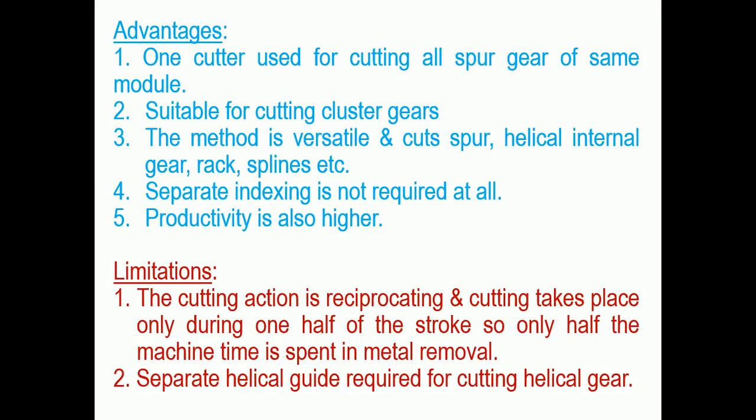What are the limitations? The cutting action is reciprocating and cutting takes place only during one half of the strokes, so only half of the machine's time is spent in metal removal, and a separate helical guide is required for cutting helical gears.